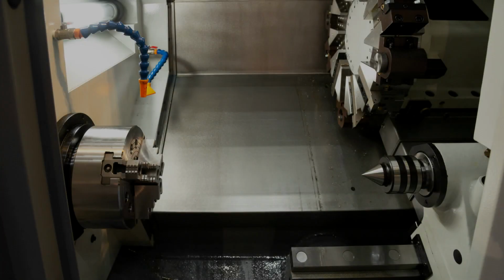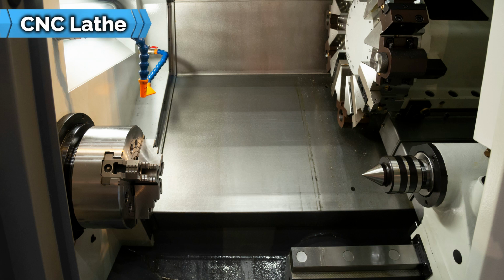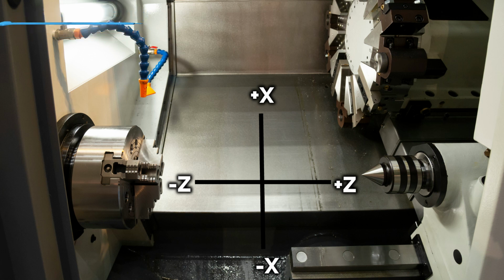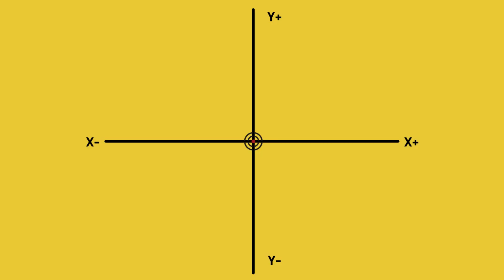On a standard CNC lathe, these axes are slightly different. The z-axis runs along the center line of the lathe, whereas the x-axis runs at a right angle from the center line of the component. Let's get back to the graph and see how it works when we are writing a program.